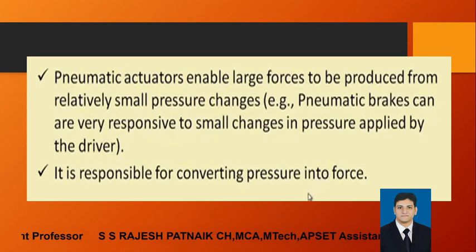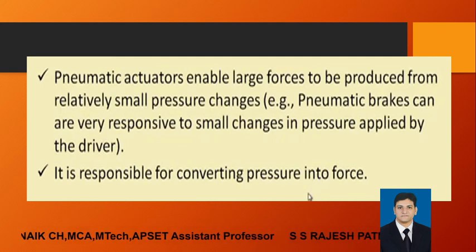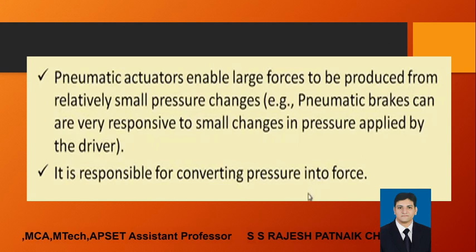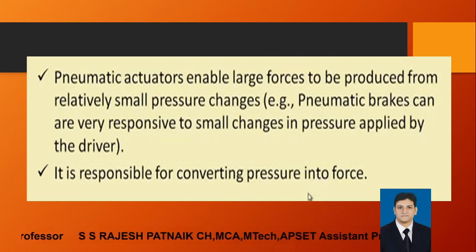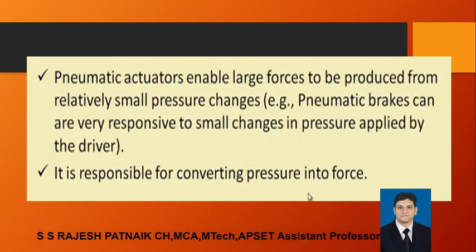How is it done? Pneumatic actuators enable large forces to be produced from relatively small pressure changes, the same thing I told you about pneumatic brakes being very responsive to small changes in pressure applied by the driver. Next point is it is responsible for converting pressure into force. Whatever pressure is applied is converted to force.